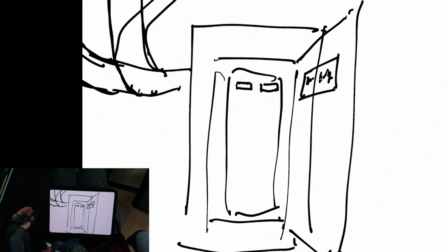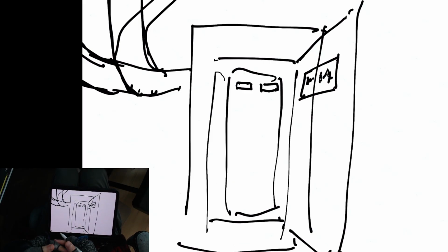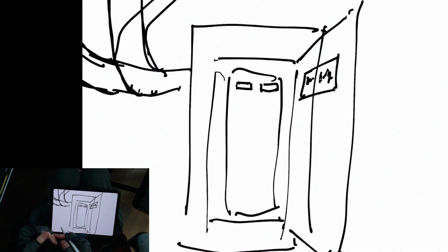If your toaster falls into the bathtub and suddenly starts drawing too much current because it short circuits, then that circuit breaker trips, or usually if you have a GFI, a ground fault interrupter outlet, a GFI or GFCI outlet in your bathroom.